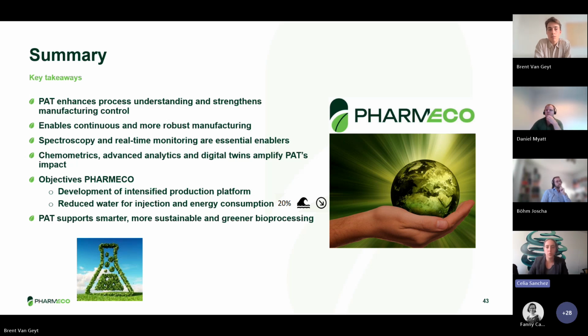This was our choice. We could have something longer or shorter, but since our process didn't change that much in 1 hour, we decided to have a new measurement every half an hour, so that the pump rate was adjusted accordingly every half an hour based on the measurement. Yeah, okay, thanks.